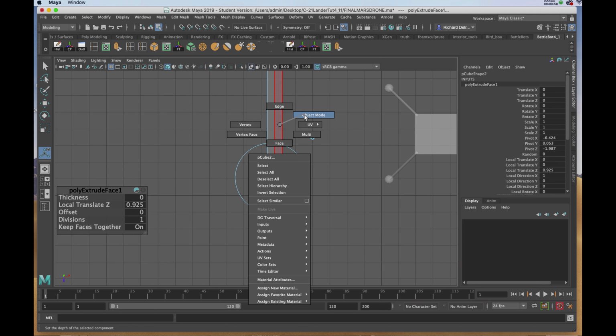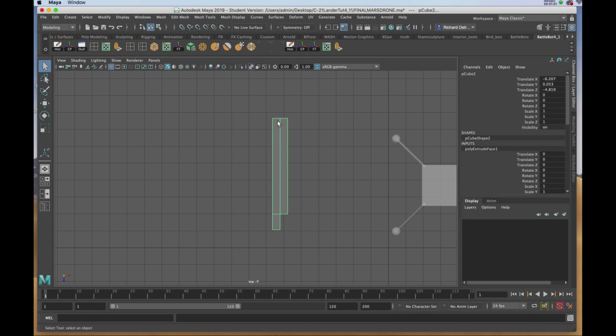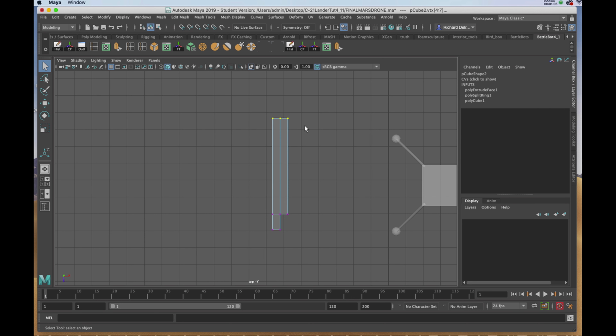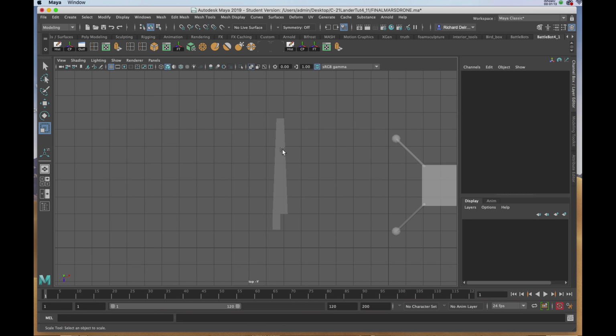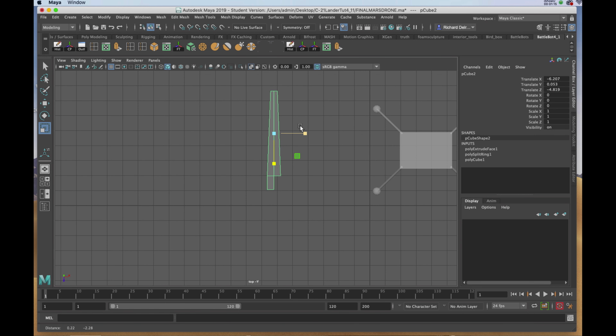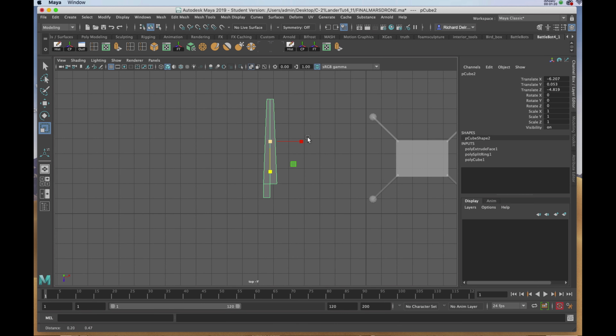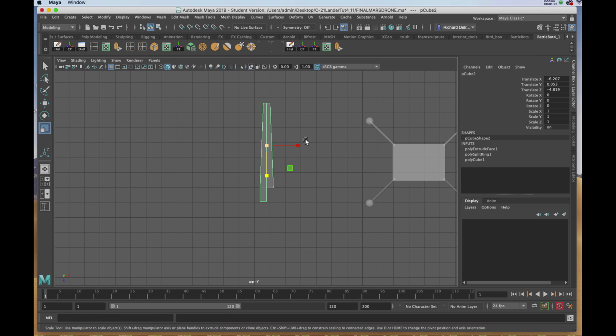I'll right-click and go back to my object mode. Now I know that should taper up on this top edge, so I'll right-click and choose Vertex, select the top vertices, and I'll hit R for scale, and I'll just taper it, and I'll return to my object mode. Now we're going to need 3 other of these as well, but I'm going to put the texture on before I proceed, so that once I texture this, all the others I generate from it will have the same UV map.